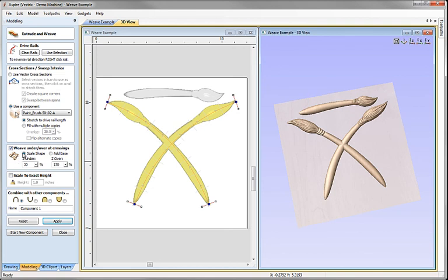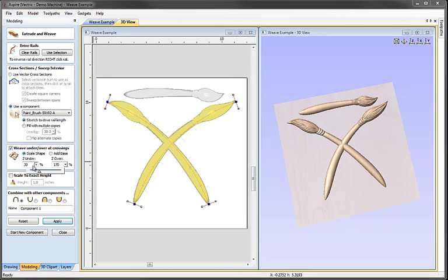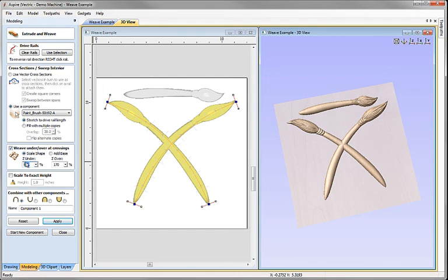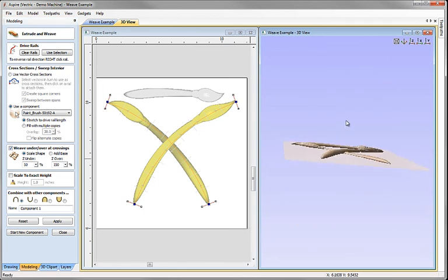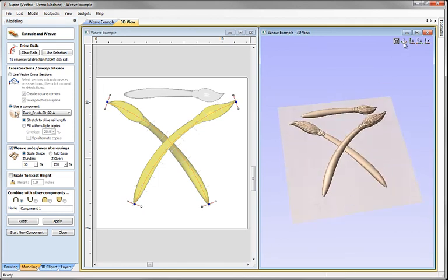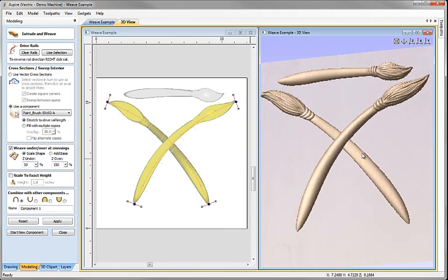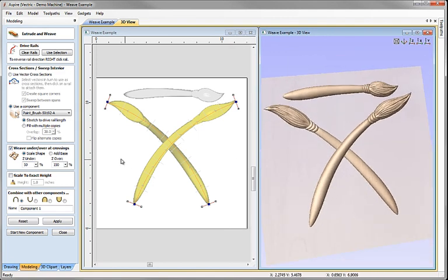In this case I'm going to choose the option to scale the shape, and we'll set this to be 50 and 150 and hit apply, and there we can see now one is being raised up and the other is being lowered down in order to get the effect we're looking for there. And we could manipulate those percentage values if we wanted to change those.